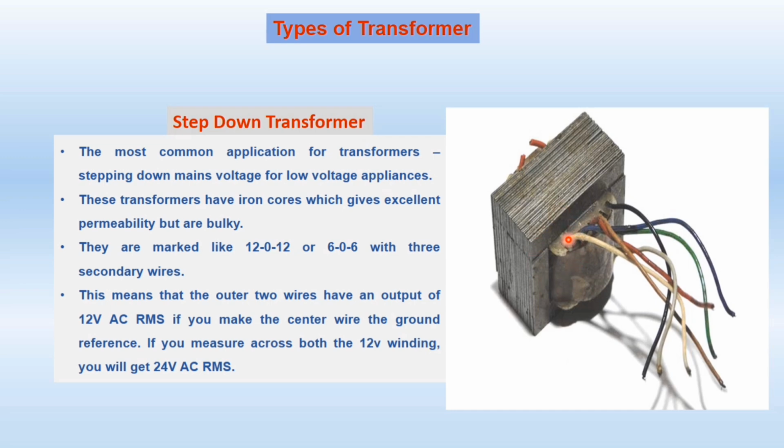So this gives you the freedom or the flexibility to choose your output voltage according to you. It gives you different options. So if you want to use only 12 volt, connect your load between the first and the middle one, and if you want to use 24 volt, then connect your load between the first and the third wire.